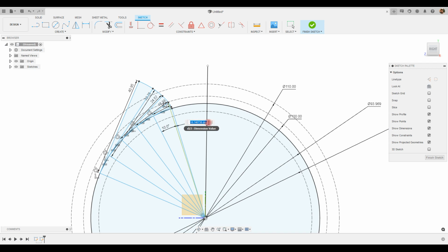This value of angle will be calculated based on the circular pitch divided by the number of teeth and then divided by 2. So based on that, we will get an arc length. Based on that, we need to calculate the angle. So let's do that calculation next.